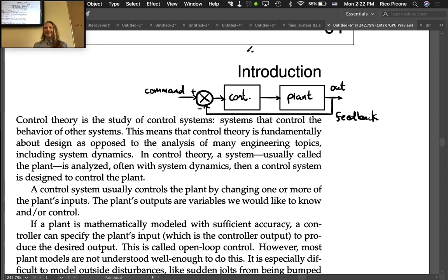So there's no feedback on it because that application doesn't require it to be precise. But the difference between 8,000 and 7,000 RPM might be very significant in some applications, and you would need to have feedback in order to do the control.